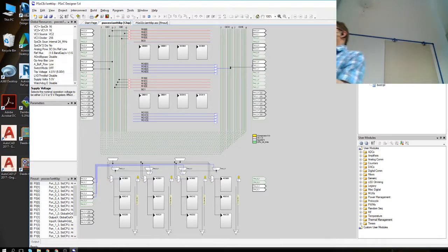Okay, flash security is about which part of this flash is used for program and which part is used for the EEPROM, for example. So you have software access also to that flash, but not to the code. You cannot actually do, well, you can, but you have to do quite a lot of work to change the code from the processor. So they try to prevent doing accidental damage to the code.